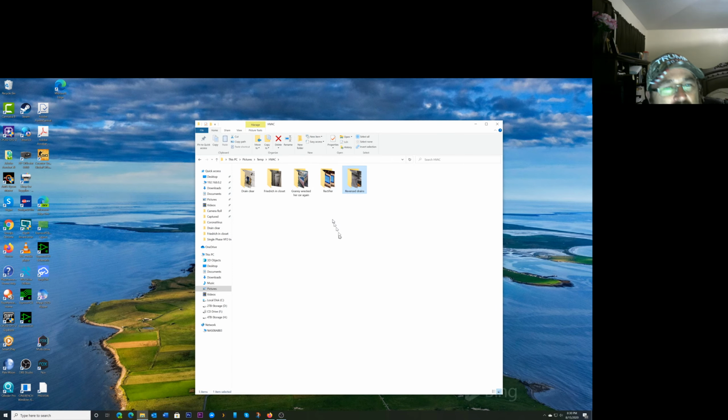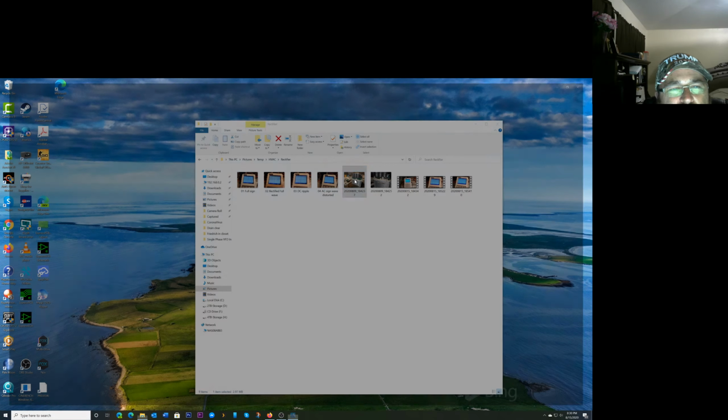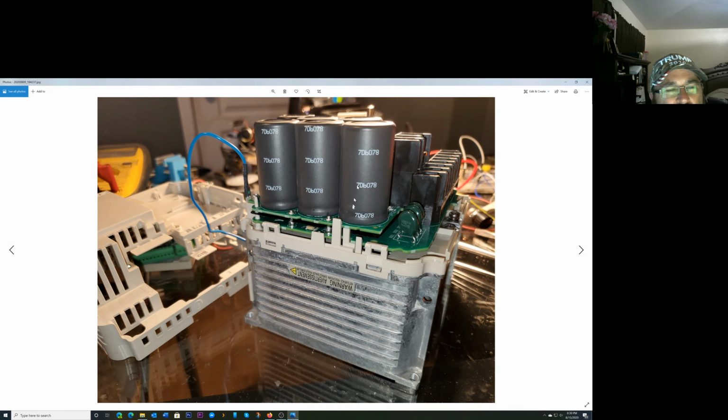So anyway, tonight, let me show you some photos I took about a week ago, but I never made them into videos. I took apart one of those VFDs. This is the same kind of VFD I've sealed into my Lennox unit. The diodes are down underneath here on this other board, and they're part of the heat sink along with the IGBT. And these boards are all soldered together.